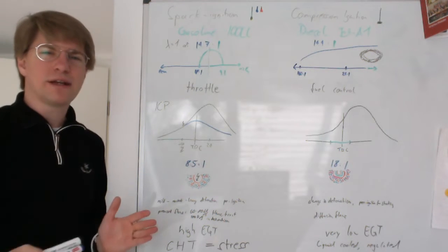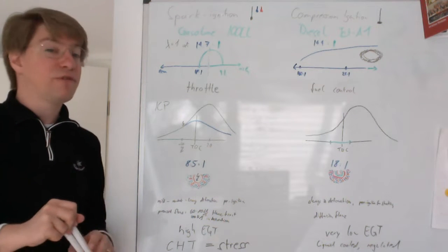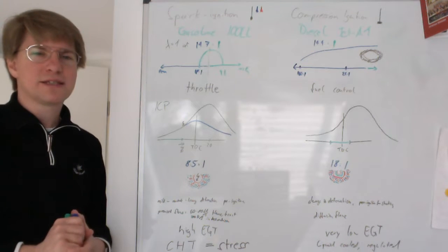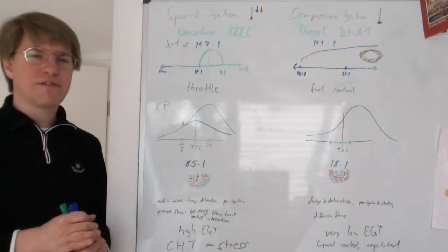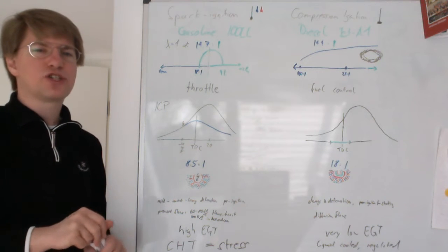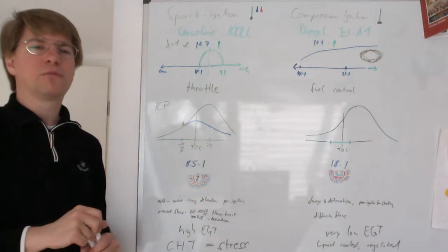So some Continental aircraft engines have what is called an altitude compensating fuel pump. So some Bonanzas, their Continental engines, have a fuel pump with an aneroid that senses the ambient pressure and lowers the fuel pump output automatically.